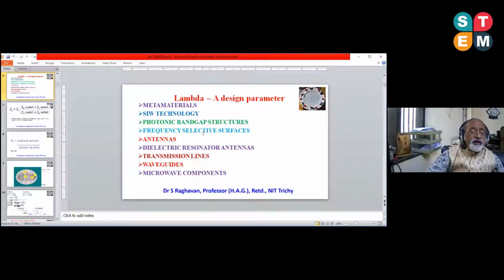Many materials, what I mean is alumina, Teflon, sapphire. Take any material, take any kind of planar transmission lines. This is sufficient. Likewise, antenna. Antenna you call resonator. Each width and the length is lambda g by 2. Only thing is because of the fringing capacitance, you remove some correction factor on the left side and right side. So in any case, it is only lambda g by 2. Now subtract some portion on the left side, some portion on the right side.